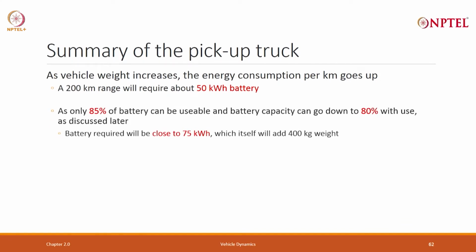As 85% is used, and finally, it goes to 80%, because the battery deteriorates, and still it should give me 200 kilometer. My requirement goes to 75 kilowatt hour. I will look at this 85%, 80% number in greater detail later on.